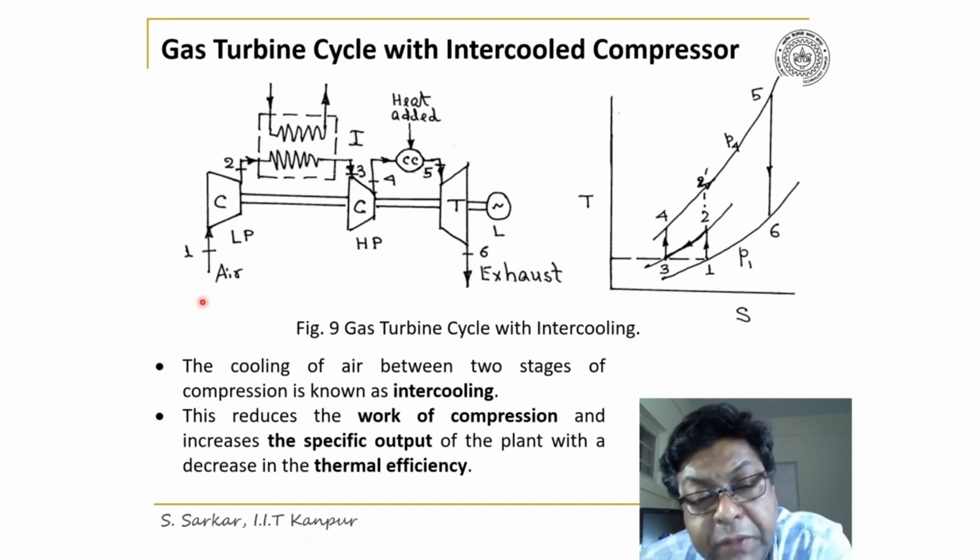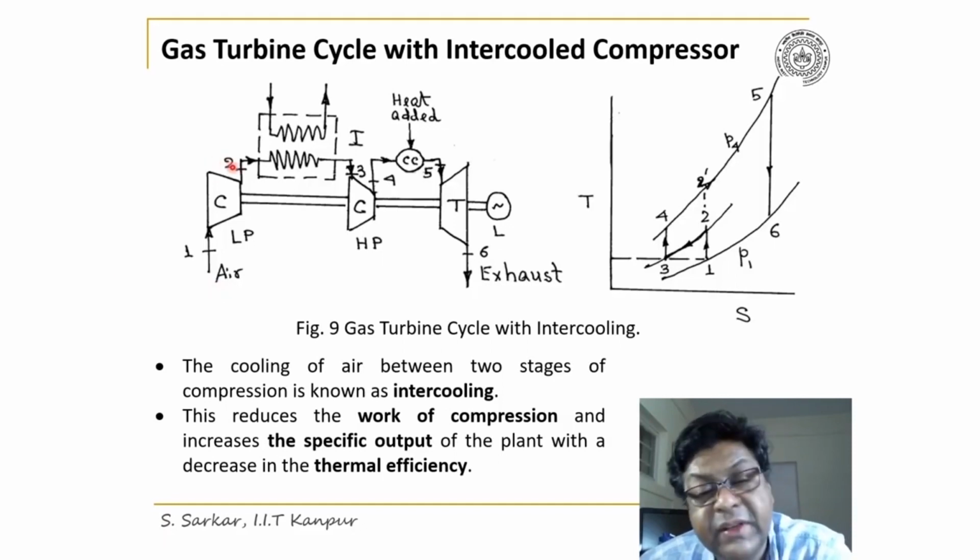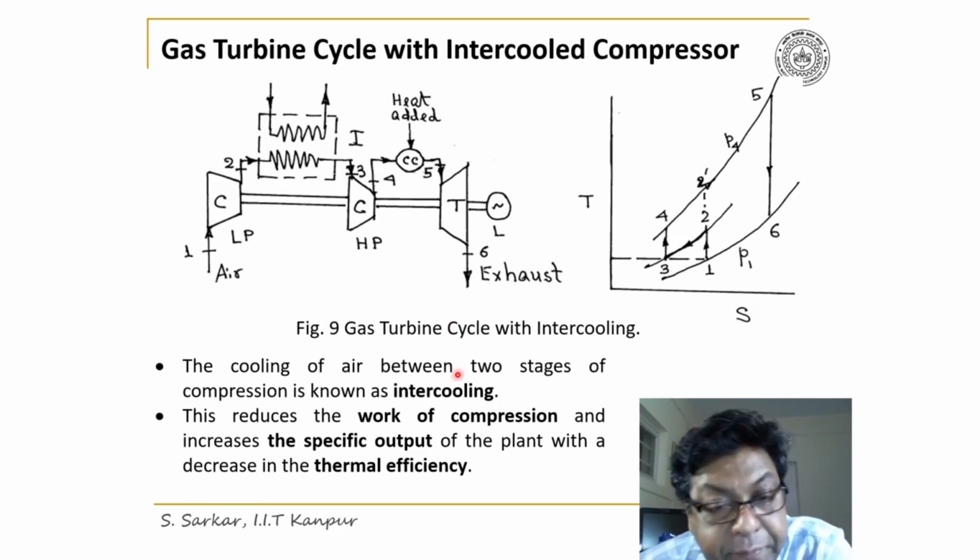So what has been done here? Air is sucked in by the LP compressor and compressed, then it's cooled in an intercooler, and then it is again compressed in a high pressure compressor, then pushed to the combustion chamber where heat is added, then it is expanded.